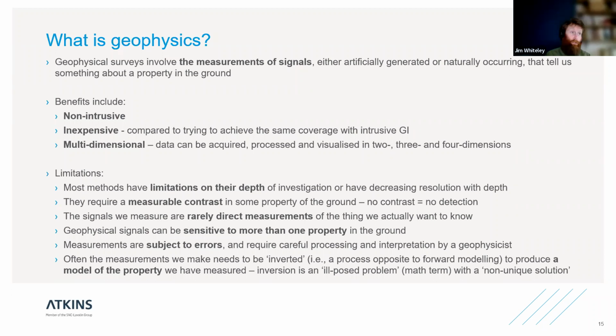So there can be some techniques where you carry the equipment, you walk it across sites, and it has continuously acquiring data modes, which can then be generated to maps, or sometimes we deploy things like geophones and electrodes, and we try to get what are called tomograms or profiles through the ground. But we either have to artificially generate those signals, or we have to try and measure naturally occurring signals. And the signals that we're interested in are tied to some sort of property in the ground.